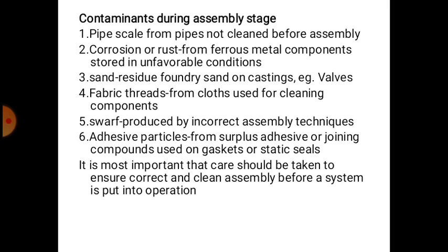Lints or fiber threads from cloths used for plugging or cleaning components. Swarf produced by incorrect assembly tools or technique. Adhesive particles from surplus adhesive or joining compound used on gaskets or static seals.